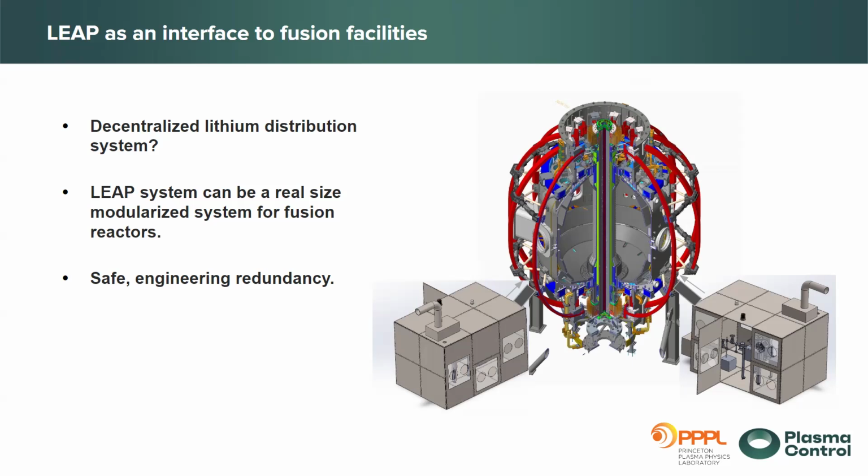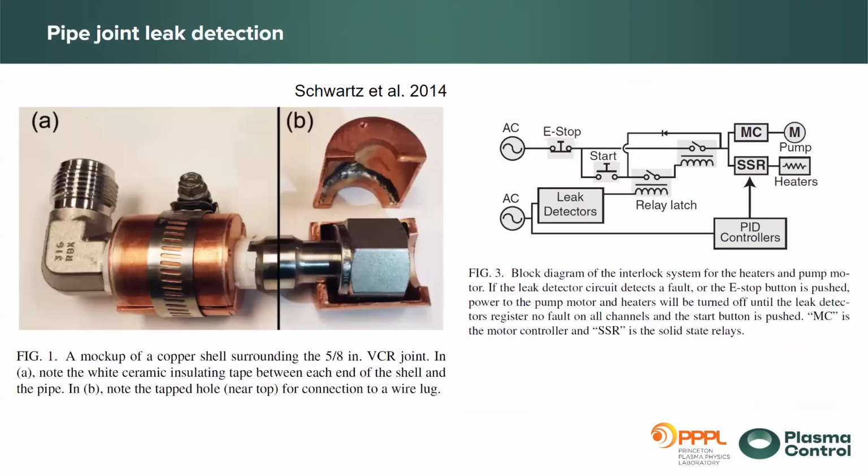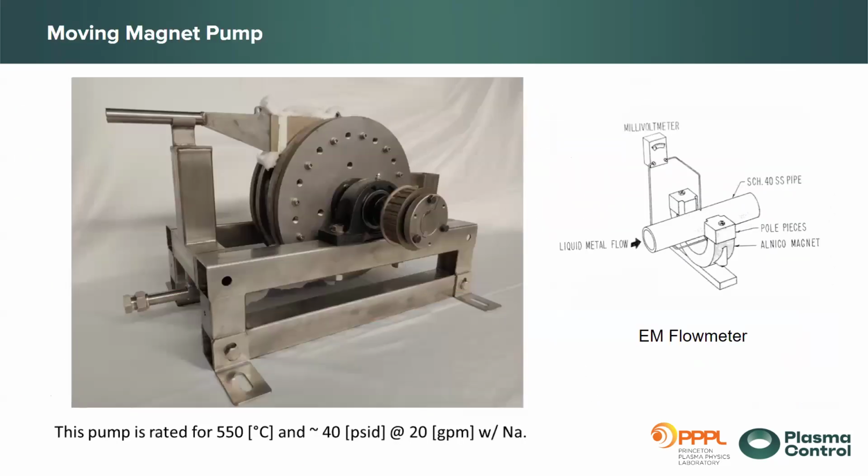That being said, for plumbing we have a moving magnets pump, which is a large pump. It's a large spinning wheel of permanent magnets that's non-contact with the liquid metal. So that provides a pressure drop pretty consistently and constantly, and that can at least transport the lithium in and out without interruptions from the B field. Yeah.